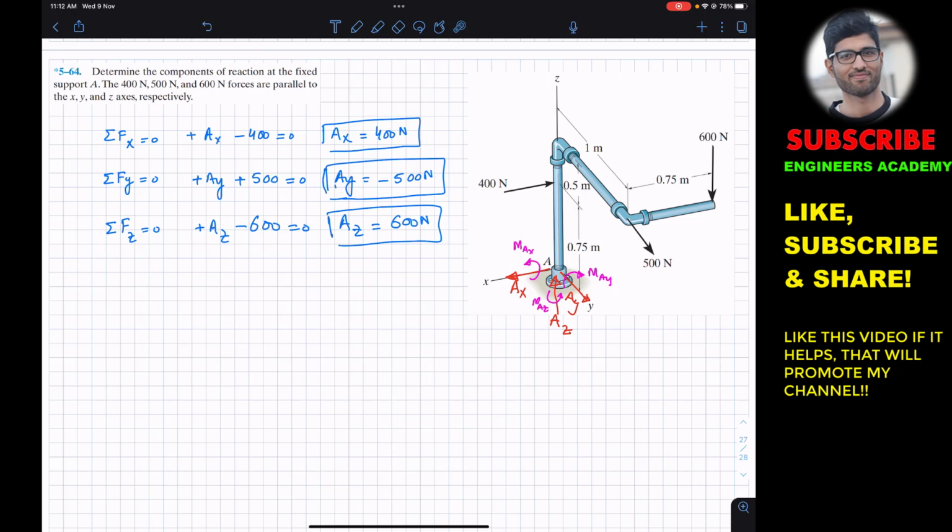Now to find these couples MAX, MAY, MAZ, we will apply the summation of moments about the X-axis. That must be equal to 0. As we can see, this 400 Newton force is parallel to the X-axis. It is not going to produce a moment about the X-axis, since it can only try to translate this whole mechanism in the negative X direction. So it is not able to produce a moment about the X-axis.